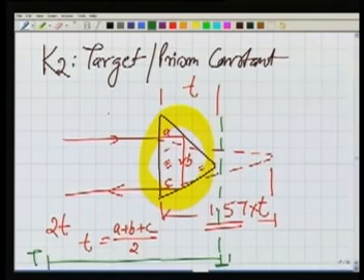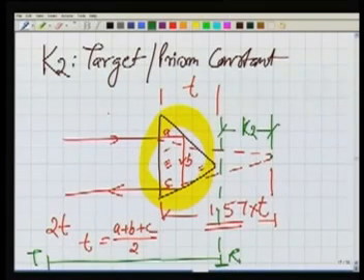I am saying the reflector is here, but actually the reflector should have been here. So we are introducing an error equal to this amount, and this is the prism constant. We need to know this prism constant and apply a correction for it. This prism constant is also known from the company from which we buy the instrument.